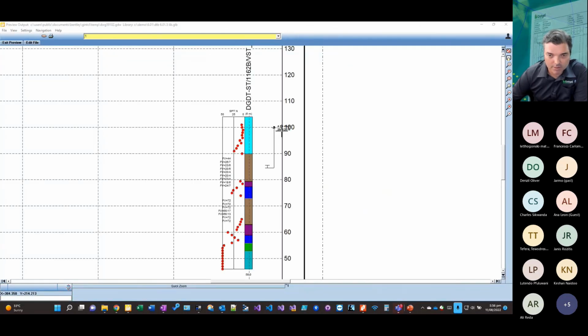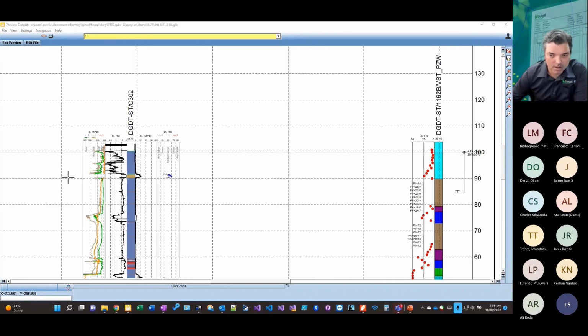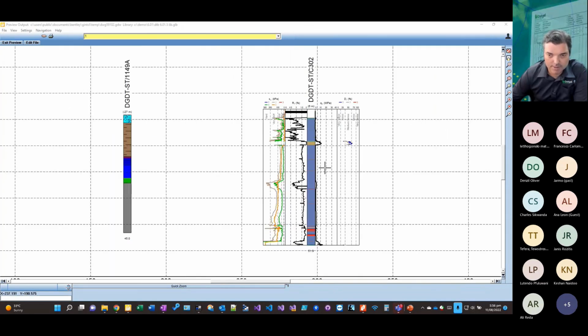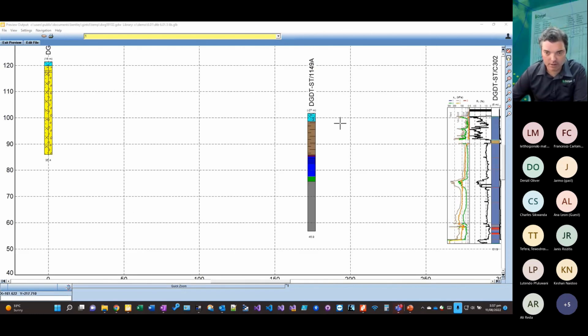So we got the piezometer levels, SPT values, geological units, the vein shear stuff. So this is the CPT, soil behavior type, results of QC and RF and SU and DR. Okay, we got the material graphic on this borehole with some material graphics on top of the colors, the geological units.